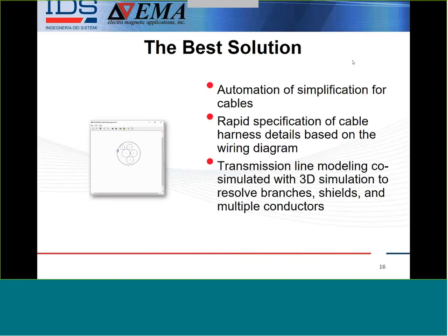They get put in early in the program. EWIS is the last thing that's typically designed. So those diameters from the CAD aren't realistic. So we actually have a better diameter estimate by packing based on the wiring diagram and then just using geometry to tell us exactly what the diameter of the cable should be.